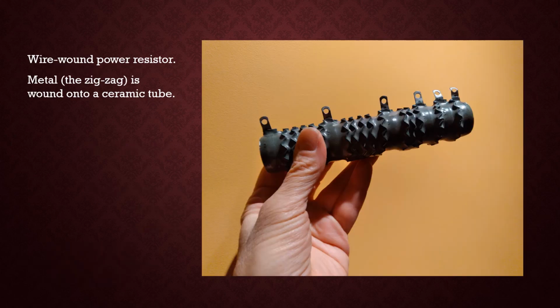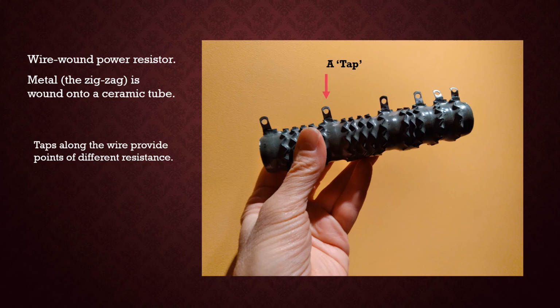So here's a wire wound resistor from my laboratory. It is a ceramic tube around which is wrapped a rather nasty looking piece of metal, and the zigzag that you see under the green epoxy coating is the wire. You'll notice that the wire is tapped. In other words, there's a connection you can make at certain points along the winding, and you can take sections of the wire and create different resistors based on the